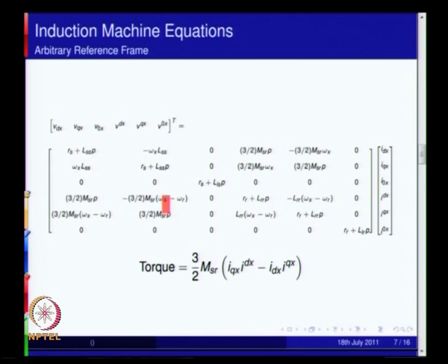If you put omega x equal to omega r, then these two terms, which are actually coils of the rotor, your reference frame is also a rotating reference frame rotating with rotor speed, and therefore they are now no longer pseudo stationary coils. The coils are really moving at omega r, and therefore this speed EMF term becomes 0.